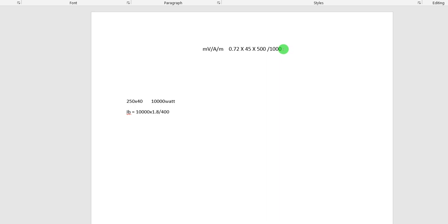So we are going to say our branch circuit MCB rating is going to be equal to 500 multiplied by a factor. Remember, it's discharge lighting, a factor of 1.8, then divide by 230. Remember, we are using 230 volts for each pole.